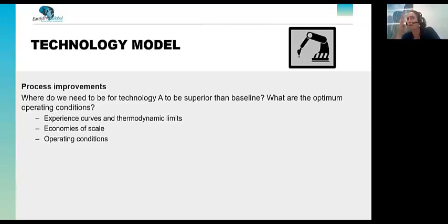Okay. So experience curves. This graph here shows single junction monocrystalline PV devices. So this is a specific line of a specific type of PV panels, solar panels. And in the x-axis we have the years, right? So we see how the efficiency of the new models has increased. We're making more efficient modules each time. And in blue, we see the range of the embodied energy. You think of the manufacturing, the energy that it takes to produce a watt of this technology.